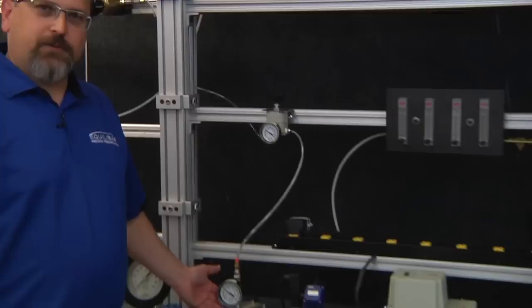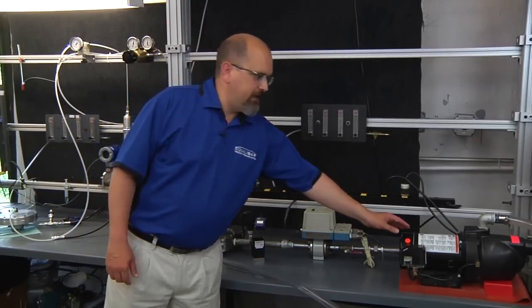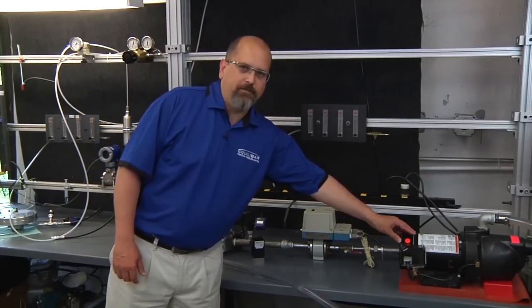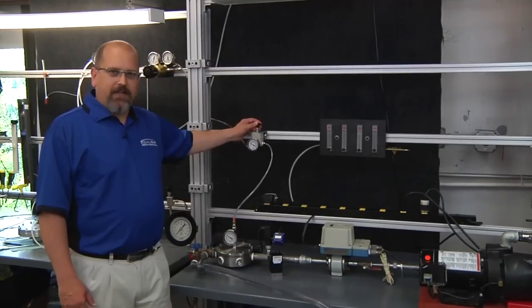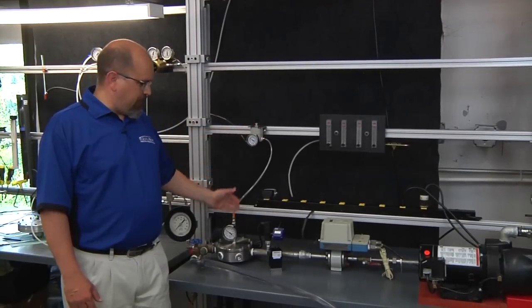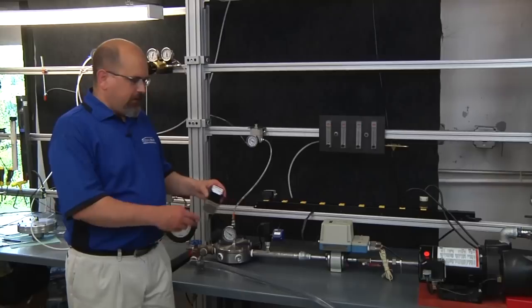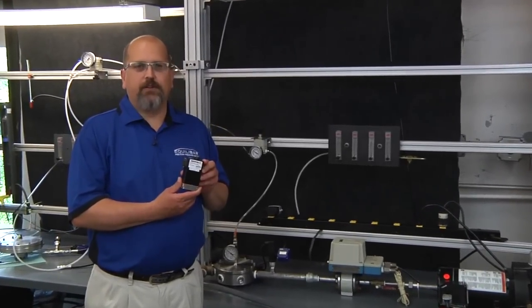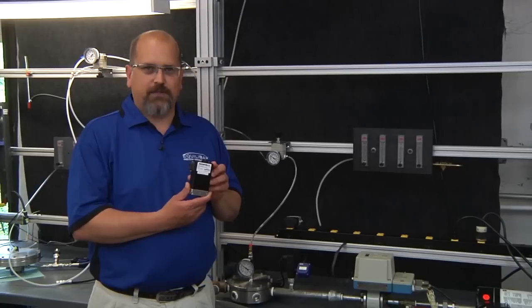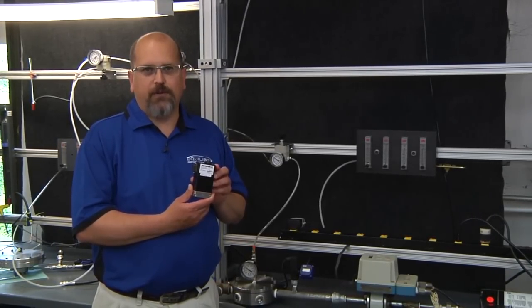So today we've demonstrated how an Equilibar back pressure regulator can be used to control the flow of any non-positive displacement pump. For the purpose of today's test, I used a manually actuated regulator to provide the pilot pressure to the Equilibar. Often, people elect to use an electronic air pressure regulator to provide the pilot to the Equilibar back pressure regulator. This can help in system automation and in remote control.